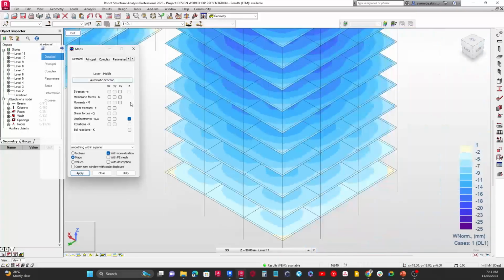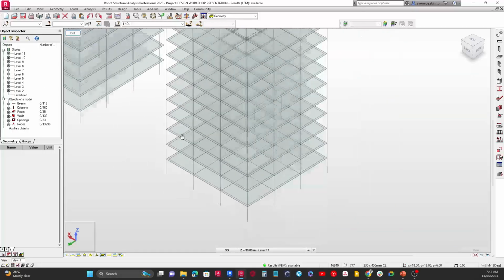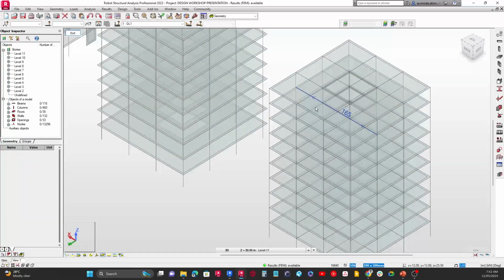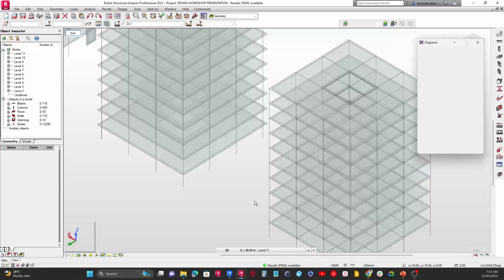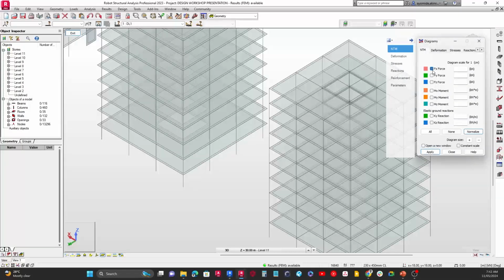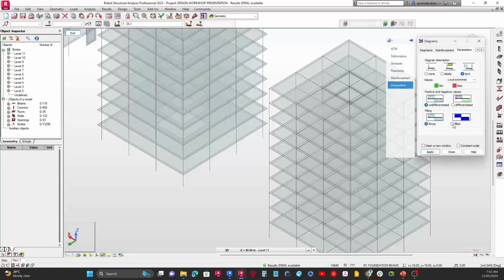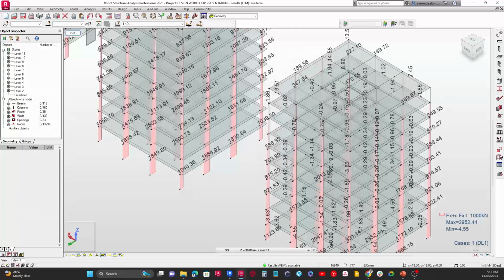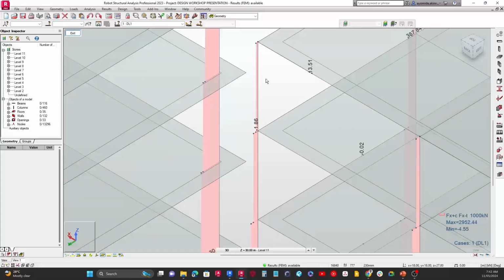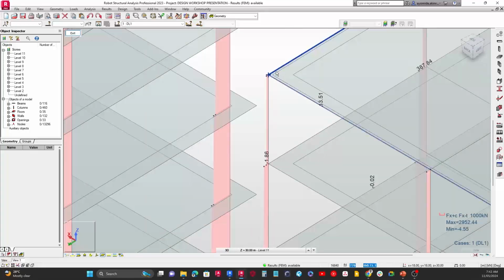And now let's go ahead and look at something vital, which is the axial forces, right? So the axial forces are basically how the loads are transferred from floor to floor to floor to floor all the way to the foundation. And to do that, I'm going to bring up another type of map. Let me come over here. All right, this is good. So we are going to be seeing an interaction diagram, how the loads are being transferred, right? So for instance, let's look at this building over here. You can see somewhere at this point over here, the load here is sent.